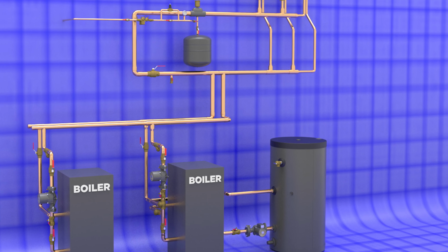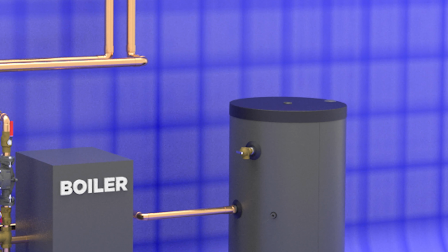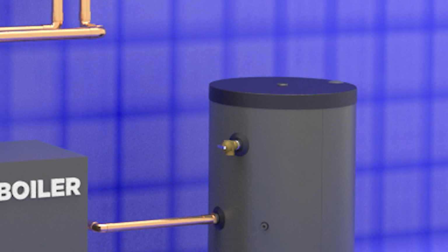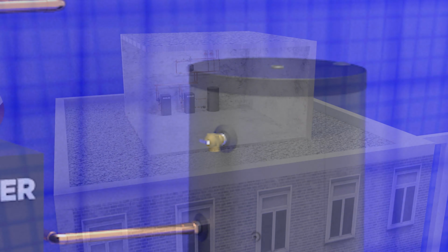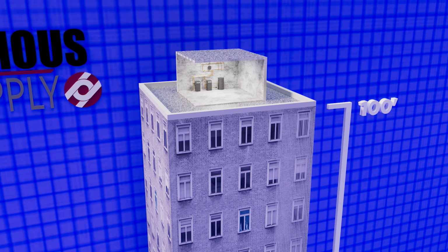This is a problem as most relief valves are set for 30 to 50 psi. High pressure on the boiler can cause the relief valve to leak or dump. This is why we place the heating equipment on the roof when we have very tall systems.